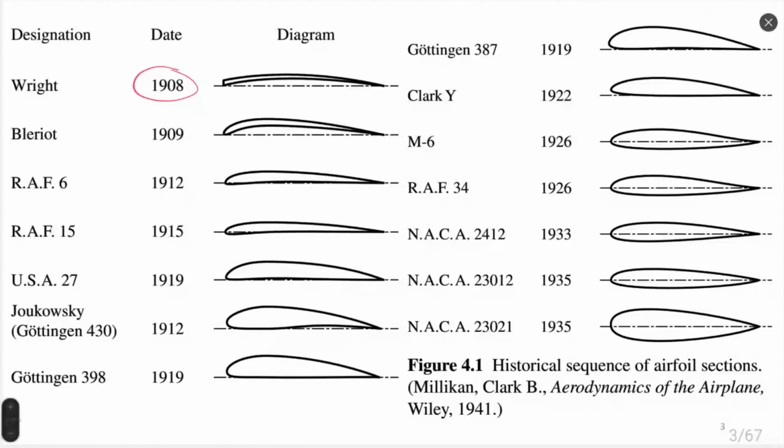Also, we can consider not just the aerodynamic point of view, like lift to drag ratio, but also the structural point of view, that airfoils have limitations by their size, by geometry perfectness, by structural strength of the wing built with this airfoil. So all these limitations result in a big number of criteria aside from aerodynamic efficiency and result in different designs of airfoils.